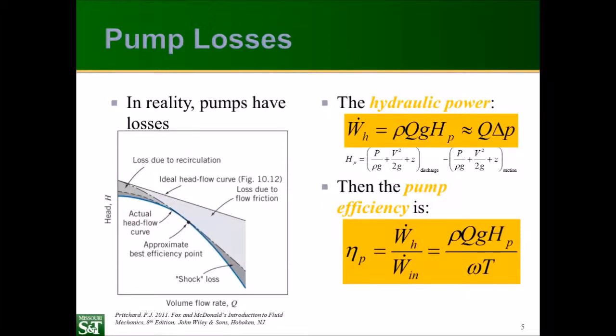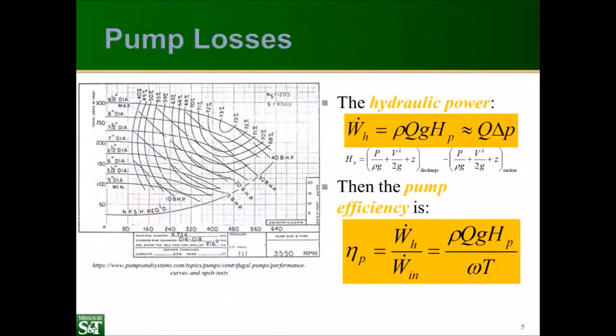And the difference between those is given by the pump efficiency. Now, all of this information can be found in typical pump curves. So at first glance, these pump curves can seem very overwhelming. There's a lot of information here. But most pump curves are created for a family of identical pumps. The only difference is that the rotor sizes change. So here we have different rotor sizes from 5-inch diameter all the way up to 8.5-inch diameter. But other than that, they're all exactly the same design. And so they all have very similar curves.